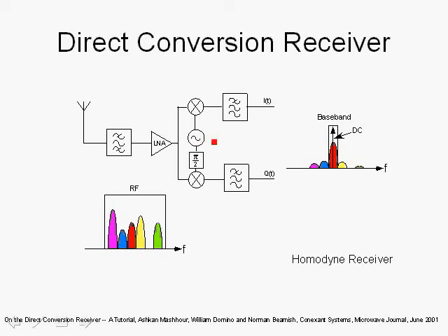We have a synthesizer that produces an in-phase term and a quadrature phase term. The filters filter out the double frequency terms, and we also have gains in the in-phase path and in the quadrature path. We've simplified things here. We'll actually show variable gains for the control via AGC.